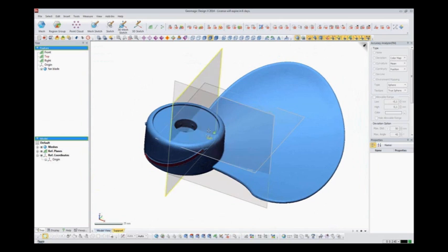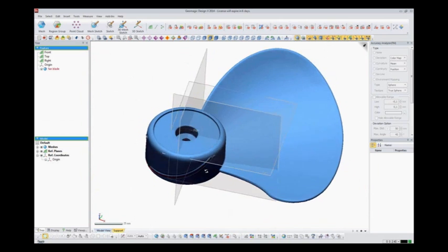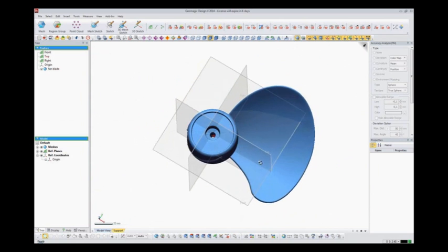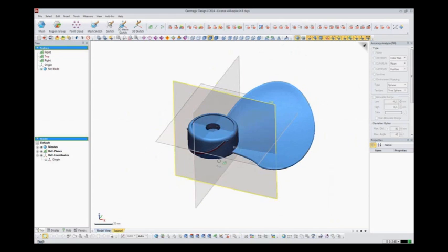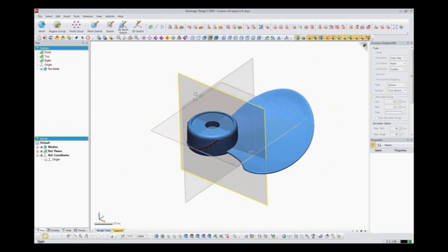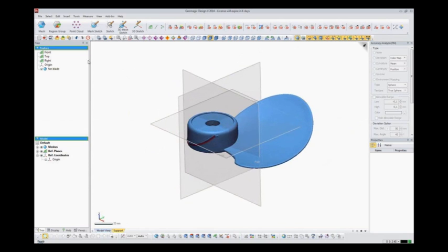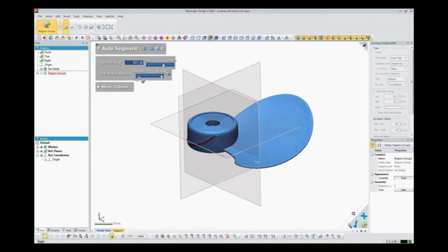So it's basically a triangle mesh. And based on this partial scan, it's not the complete fan, it's just one blade, we will generate the complete fan from this model. And to do that, first I will check the model for separate regions.